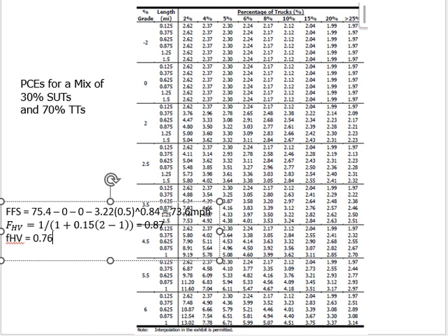The length again, same thing. It doesn't go up to 2. It goes up to 1.5. So I pick the value from here, and my percentage of trucks is 15%. So the value is 2.04. If you go there, you will see in the last column the value stops changing. This is an indication that after this, the value will remain the same. So now my value is 2.04.